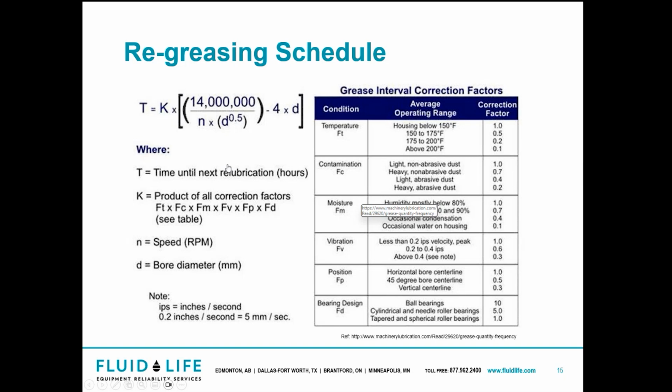So with our calculators, we have a factor for intermittent operation, whereas this calculator here is constant, 365 always running. Using those kinds of values, you can see how often you should be greasing and with how much grease. So for example, 5 grams of grease every 3 months.